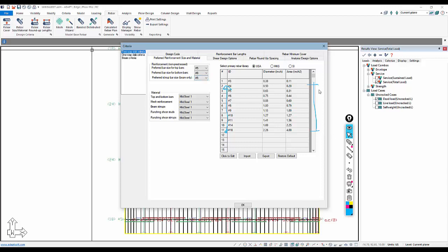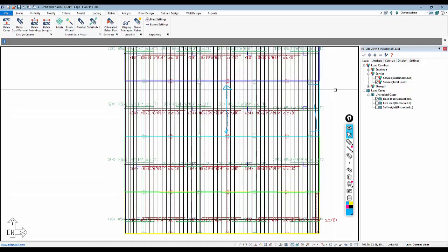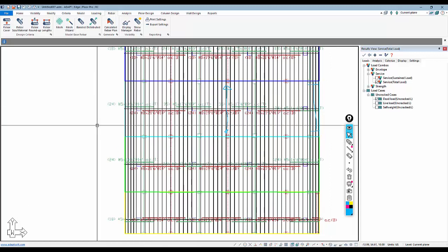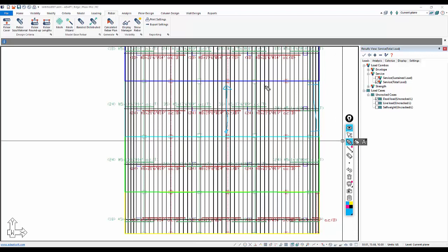Okay. So if we look and see where the misalignment is, let's say, between the bars shown here and the calculated required number of bars, which is 8. We have 24 shown, but we just showed that we need only 8 bars. So if we assume that one of the 8 bars is aligned here, I'm just going to draw this. There's another bar here. So those are 2 bars. And really we need to fill this in with an additional 6 bars.